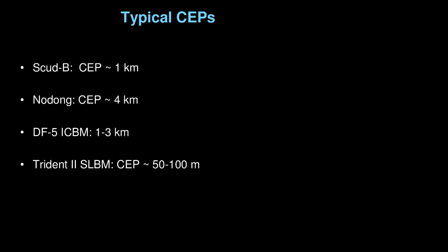And so at that point, you've worked very hard to do as well as you can on guidance and control. You've mapped out the gravity field of the Earth, so you know what to expect when you're calculating the trajectory. You've got a very high beta warhead that is as symmetrically controlled going through the atmosphere as it can be, and you're trying to use what weather reports you have about the target to take into account whatever you can about the conditions around the target. In terms of terminal guidance, let me just finish with this.